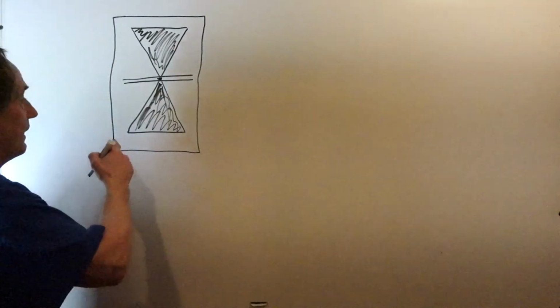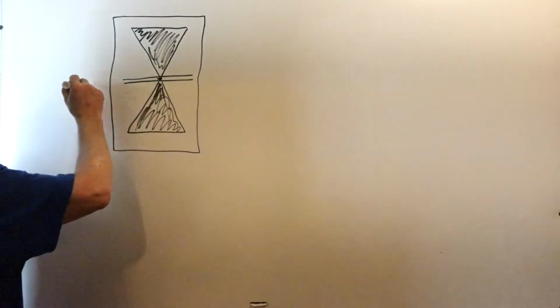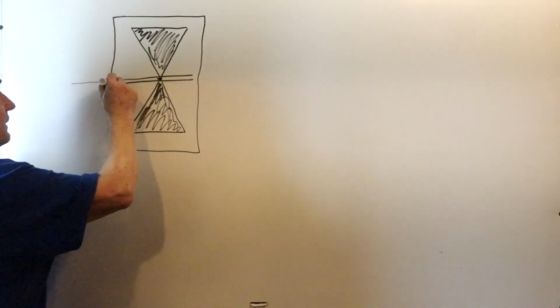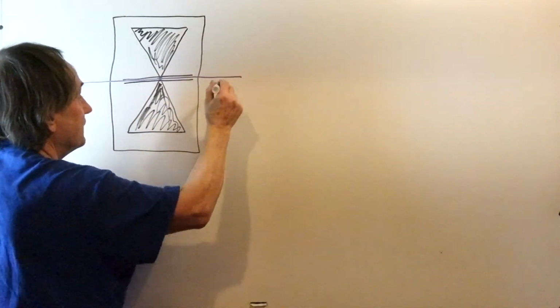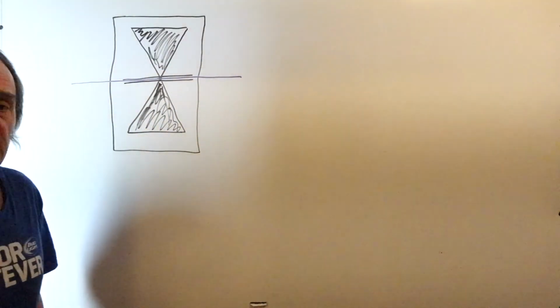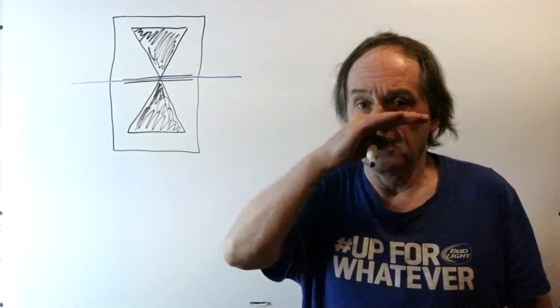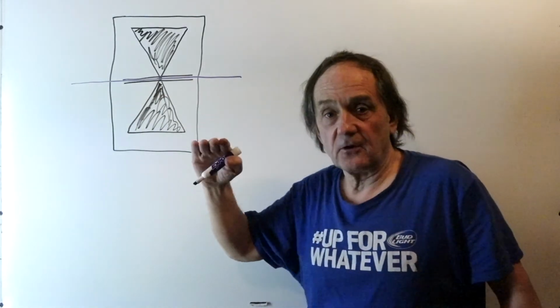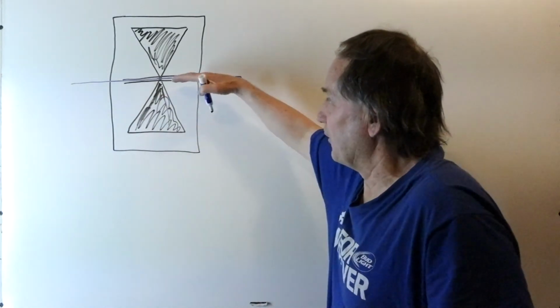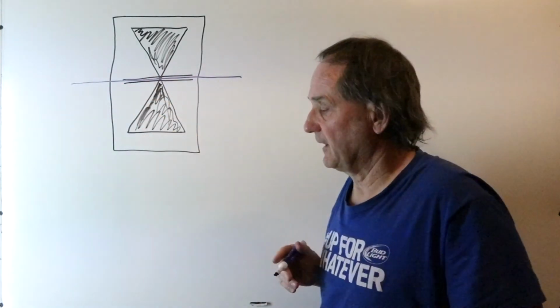And what we're trying to do is get these targets aligned so that the center of the targets are aligned with the horizontal crosshair of the auto level, so that we know that the target is on the tangent line.